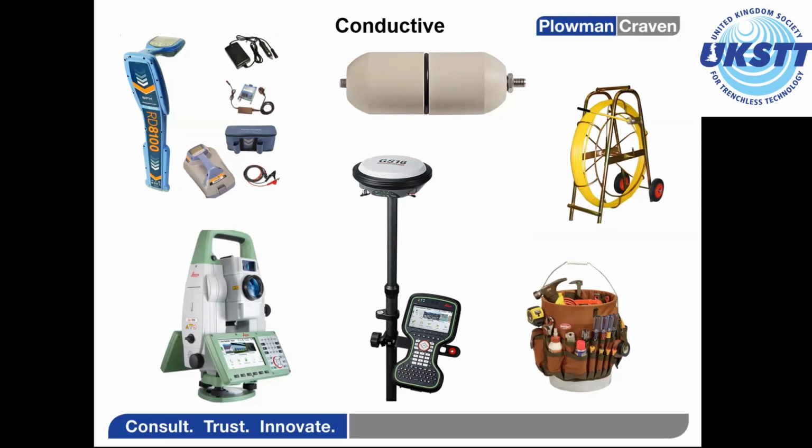When tracing cables, we use EML, electromagnetic locators, or Cat and Genny, as they're commonly known. The Genny part of the equipment allows us to induce a signal into the ground, which is picked up and carried by the metallic or conductive object. The receiver measures these signals and, with the internal antennas, allows us to calculate a depth.